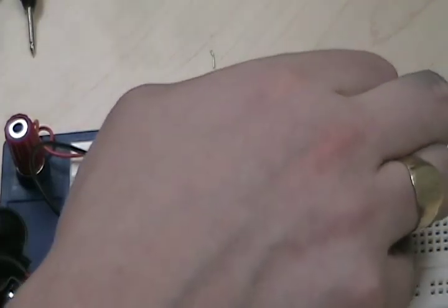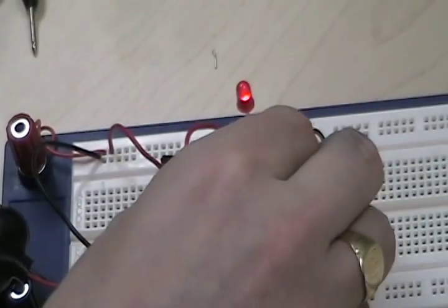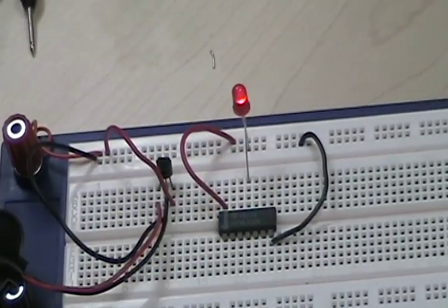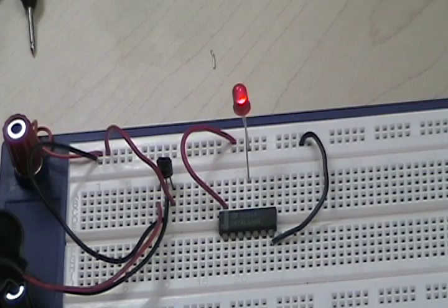Now notice something. If I take both of the inputs and leave them alone, don't plug them into anything, the output stays high. I'll tell you why that is. Because with TTL, with digital circuits, normally, not in all cases, but most of the time, if an input is not connected to either 5 volts or 0 volts, by 0 volts I mean a very low signal or the ground line, then it will automatically assume a logic of 1.